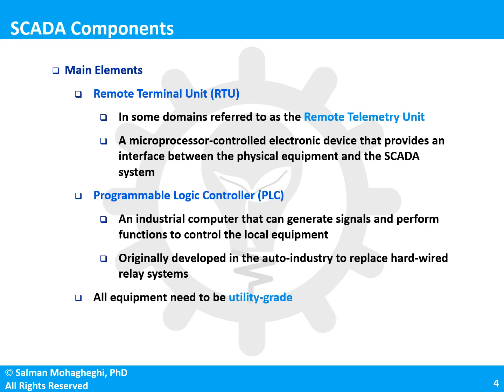We also have the programmable logic controller PLC, which is basically an industrial computer and directly connects to the physical equipment, can extract measurement data from that equipment and send it to the host computer through the communication network of the SCADA system, or, for example, can receive commands and set points from the SCADA system and then implement it locally at the equipment level.